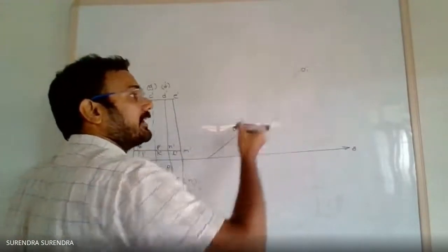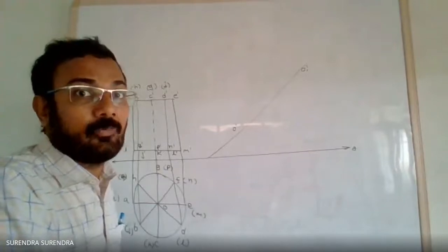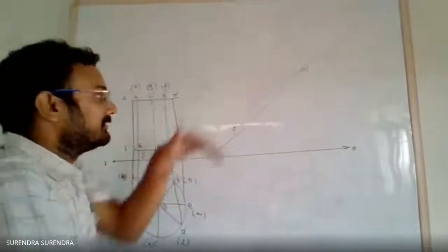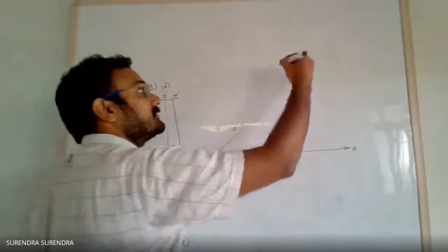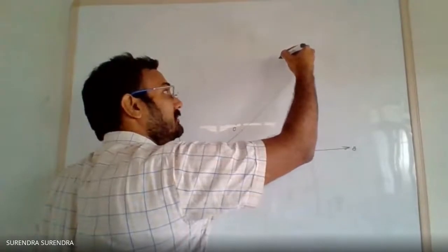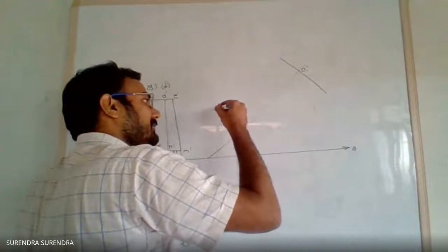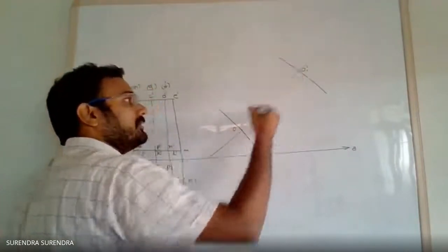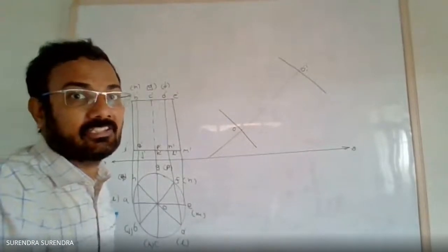Now at these 2 points, draw a perpendicular line to the axis, because the base is perpendicular to the axis. These 2 points must be at a distance of 80 mm, the axis length.